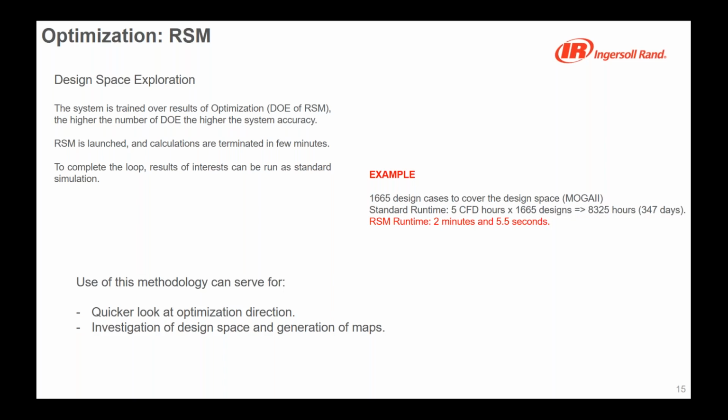So here, if I would like to explore the entire process flow that I have seen, I ended up with 1,665 design cases to cover the space. And considering that a single CFD for that specific case was running in 5 hours over 32 cores, I would have to run for exploring the entire design space in 347 days.